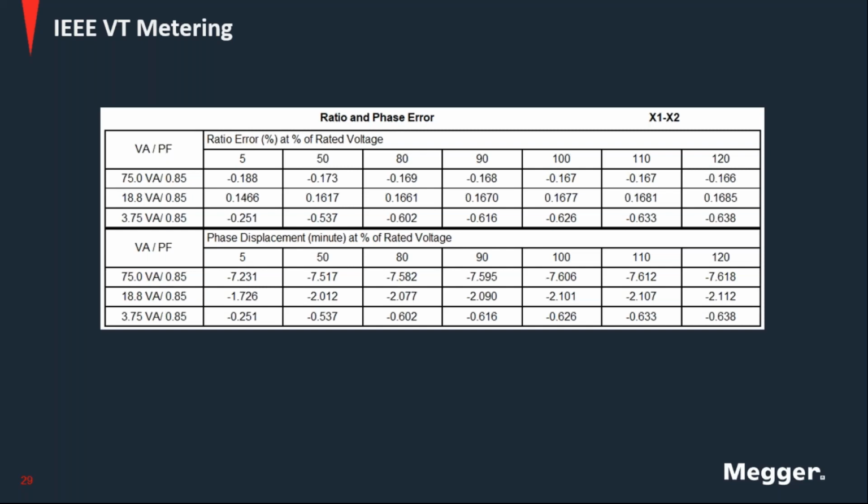In this case, whoever ran this test did not measure the impedance of the circuit connected to the CT, so we don't have the actual evaluation at real burden conditions, but still you can see how linear the behavior is throughout the range of the instrument transformer.